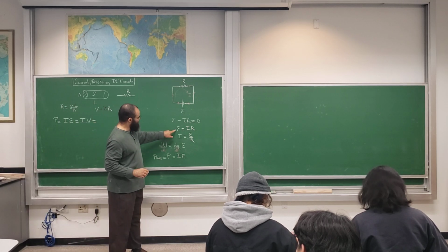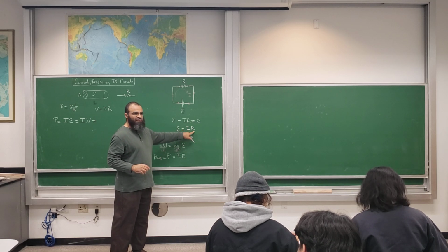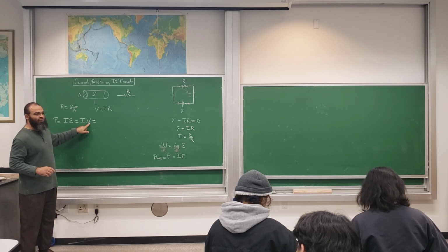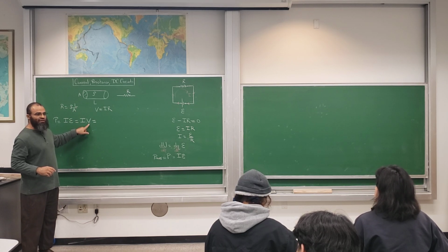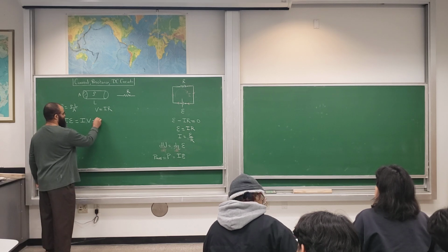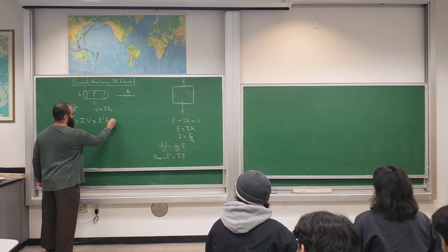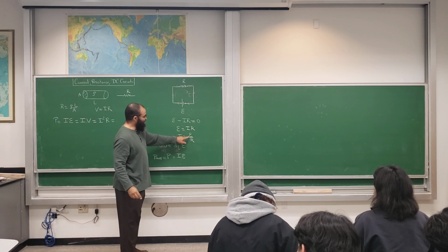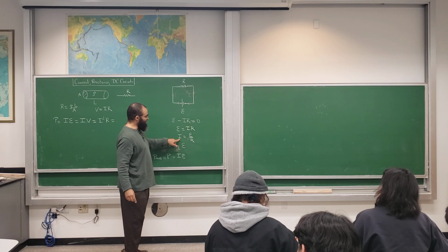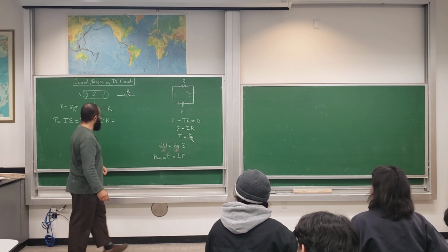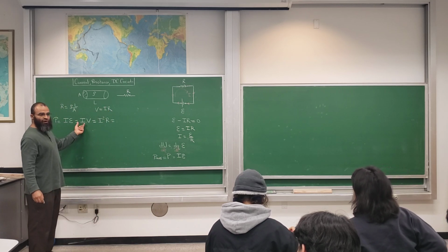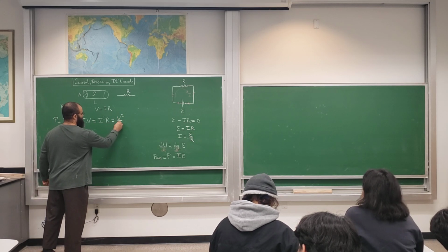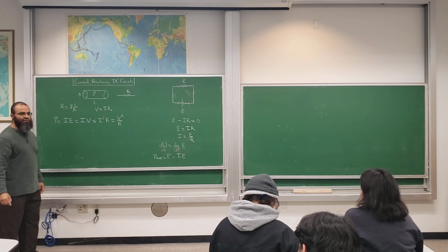The voltage or the EMF is IR, right? What if I replace this V or the EMF by IR? I times IR, what do I get? I squared R. Let's put another equal. Now let's replace I by V over R. If I replace I by V over R, I get V times V over R, which is V squared over R. So these are different ways to find the power.